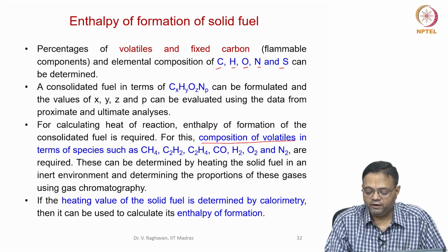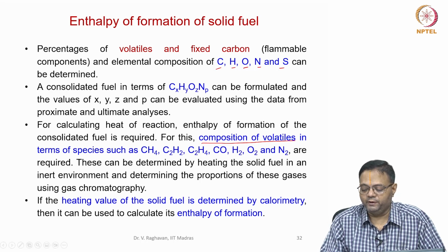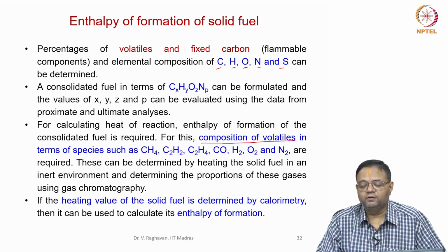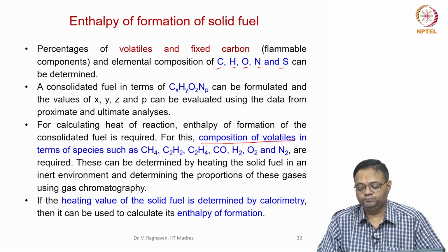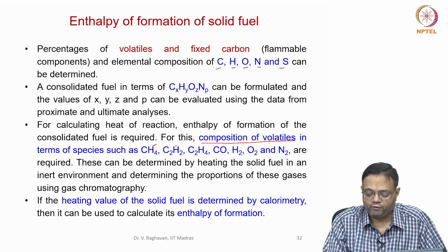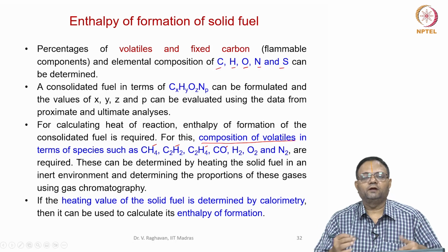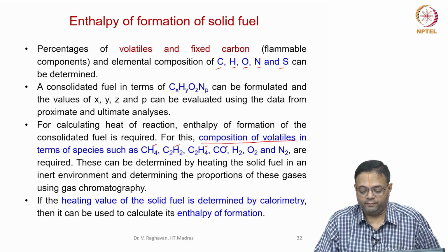See, for example, if the composition of these species is known as volumetric percentages, then I can calculate the mole fractions, and mole fraction into enthalpy of formation of each species can be done. Specifically, I need the enthalpy of formation of these species, which is known to us. So, from that the mixture's enthalpy of formation can be calculated.